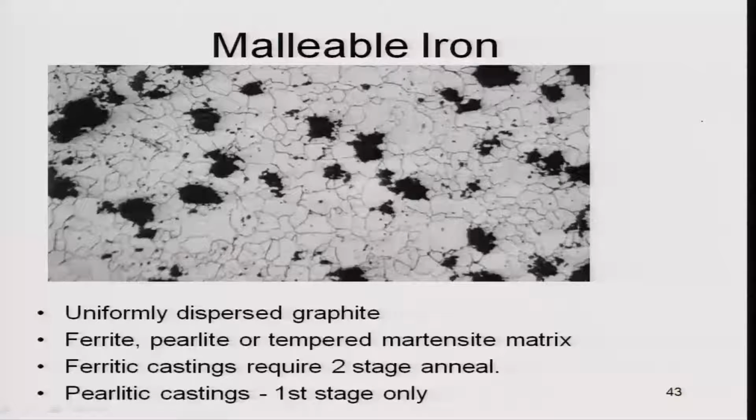So, in the last lecture I discussed ductile iron, or nodular iron. Now, I am going to discuss malleable iron, sometimes known as vermicular iron. So, what is it? Malleable iron is a solid state product. First of all, let me tell you, grey iron, spherical graphite iron, and white iron are all produced from the liquid, but this is a solid state product.